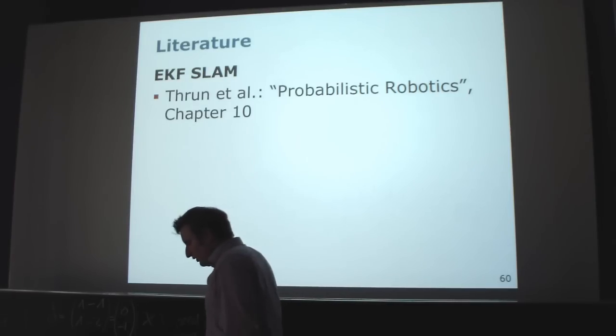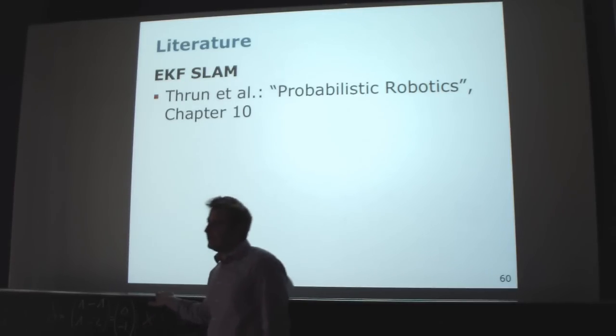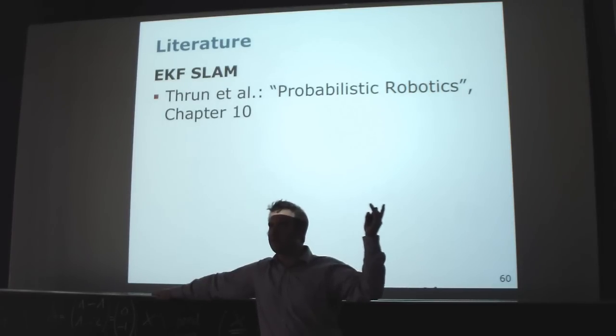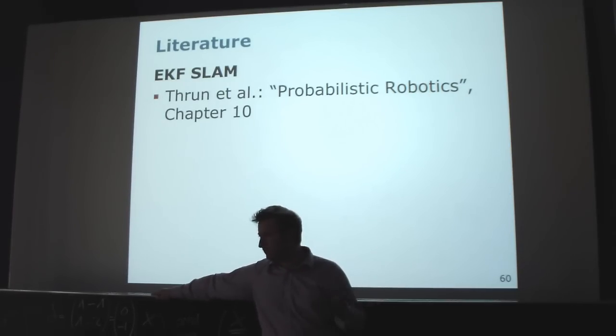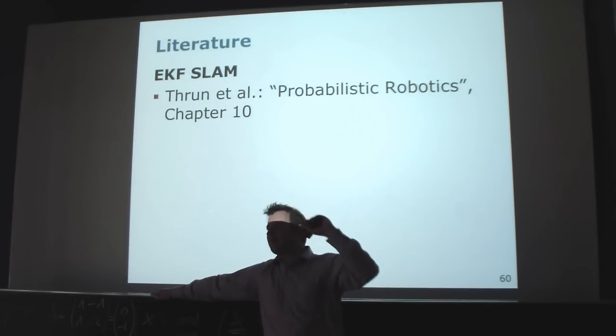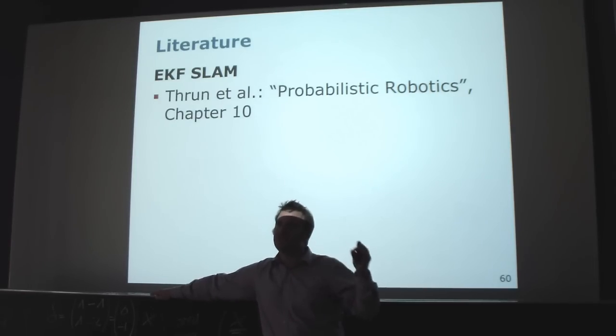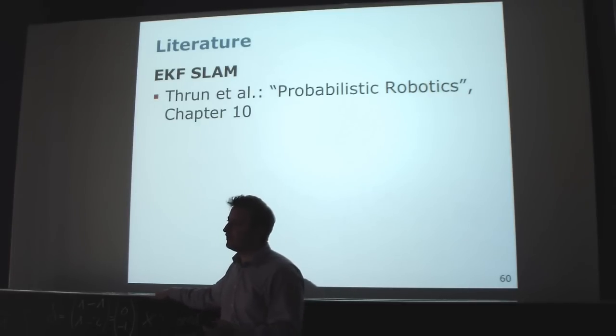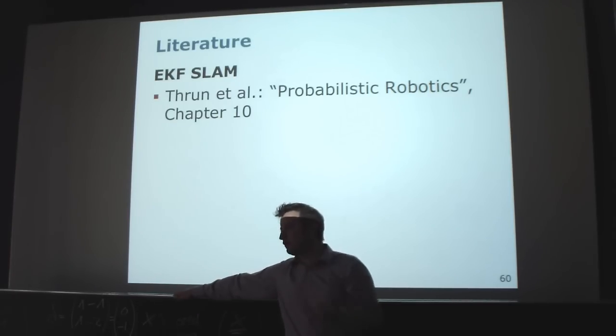So you need to allow, in general, the path planning or the motion planning system to find its way. You can do that by either providing some rough sketch map or very abstract map, or something you can download from OpenStreetMap or from Google Maps to have a very rough reference of where to go. You may provide GPS, which has significant uncertainty, especially in urban environments. But you know at least roughly where to go, and then you can build up your accurate map.